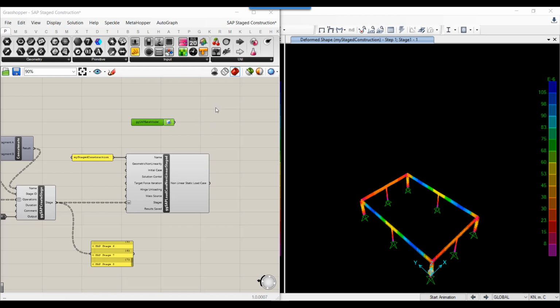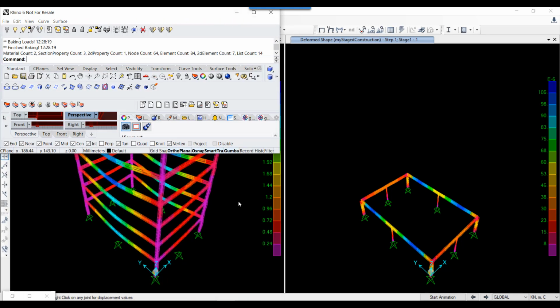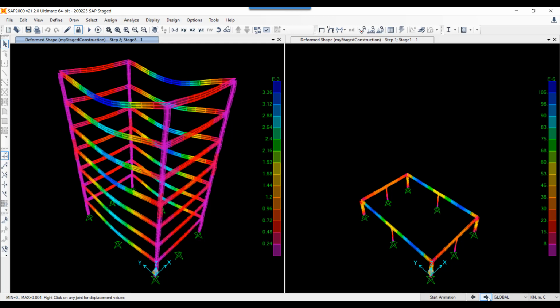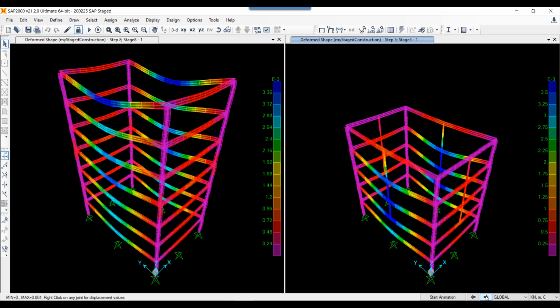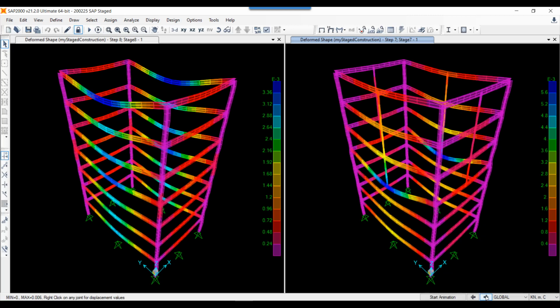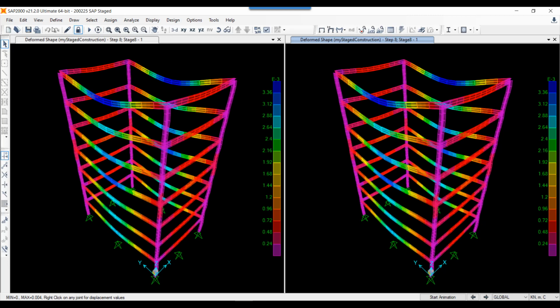I just want to go through some of the enhancements we've recently made to the SAP2000 structural analysis plugin, which allows you to automate the generation of stage construction stages as well as operations for loading, object adding, and object removal within those stages. Basically, to do something simple for just a stage construction, where you might want to add loads, add props, and remove props during a stage construction sequence, similar to this example that I show here.